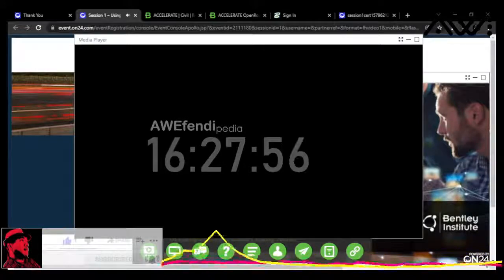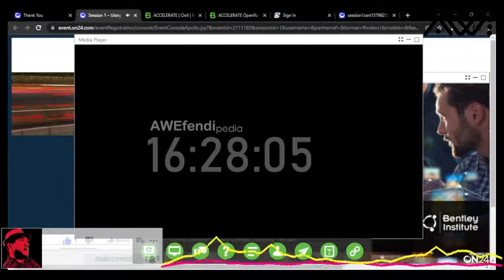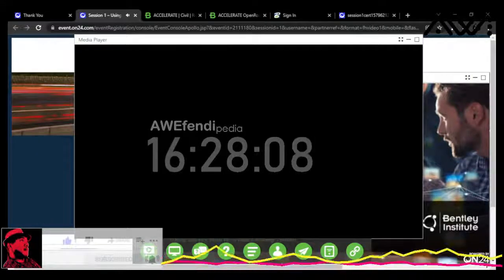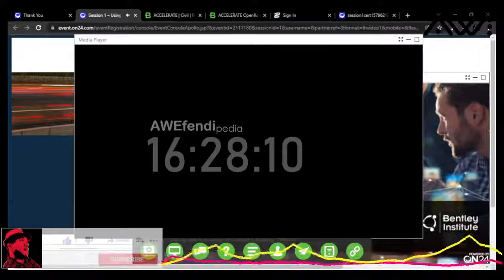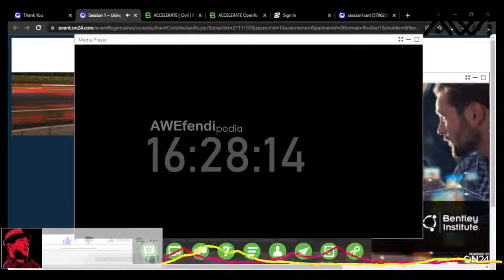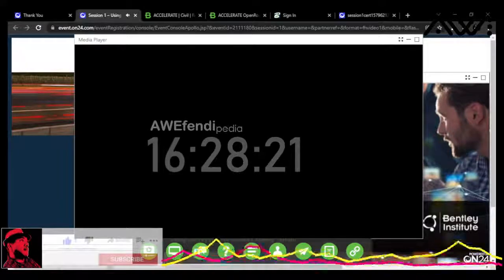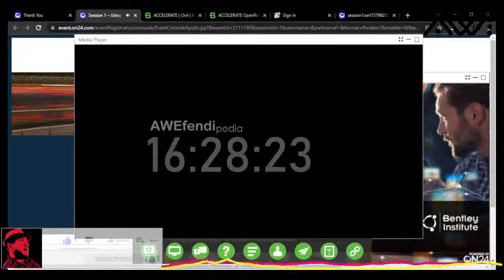Let's just have a look at how this looks in 3D. Let's do a rotate view, move our locator point to somewhere around our bridge deck, and let's move it in 3D. Okay, so as I zoom into my bridge deck, I can see I kind of have a problem with my terrain model in that I really don't want my bridge deck features to be included in my terrain model. In this case, I just want an existing ground topo here. If I want a terrain out of those, I can come in later and create a terrain from graphics by choosing those. But right now, I don't want those included in my existing ground terrain.